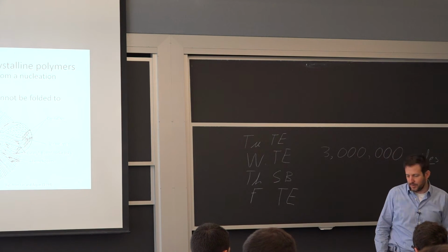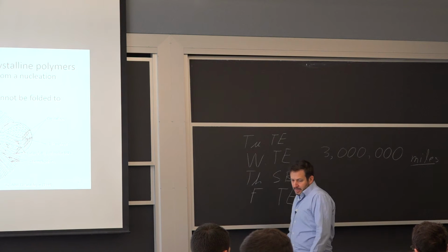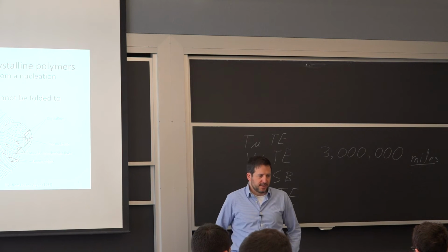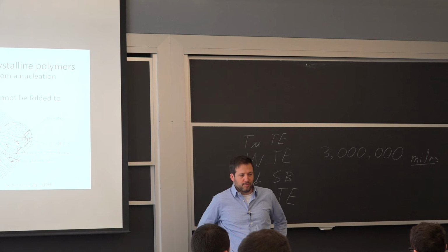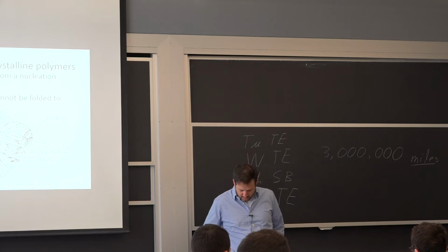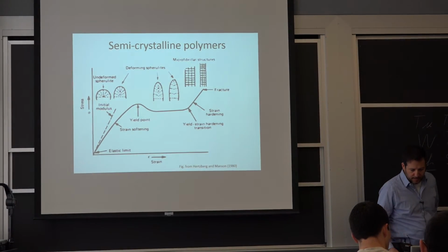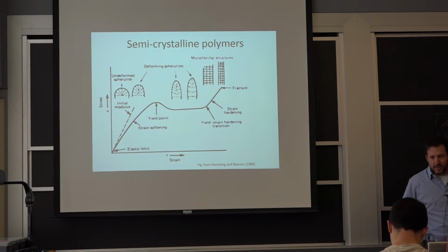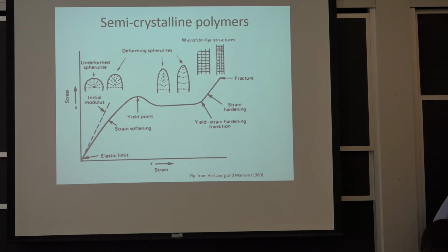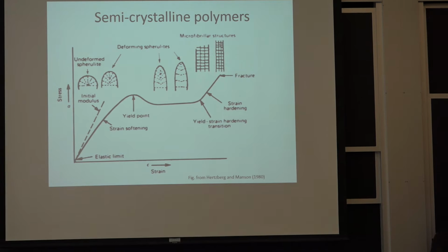It was in service for a number of years, but there was some concerns, to say the least, about the long-term longevity of that. So when we have the opportunity, if we want, I didn't bring the pipe sample. Next time. For pipes, a lot of time they are extruded, so they essentially are cast into this spherulite structure, and then the next step is to draw it. That's what you have nylon cords for too.